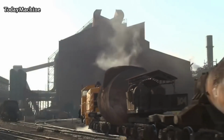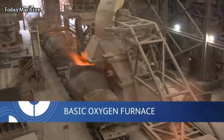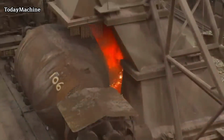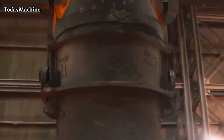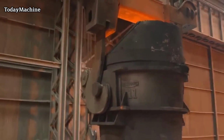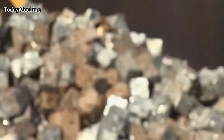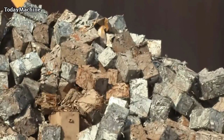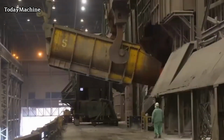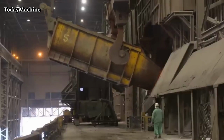Limestone is another essential component in the steelmaking process. It is added to the blast furnace as a flux, which helps remove impurities from the molten iron. When limestone is heated, it decomposes, releasing carbon dioxide gas. The carbon dioxide reacts with the impurities, such as silica and other non-metallic compounds, forming slag. The slag floats on top of the molten iron and is periodically tapped off from the furnace.